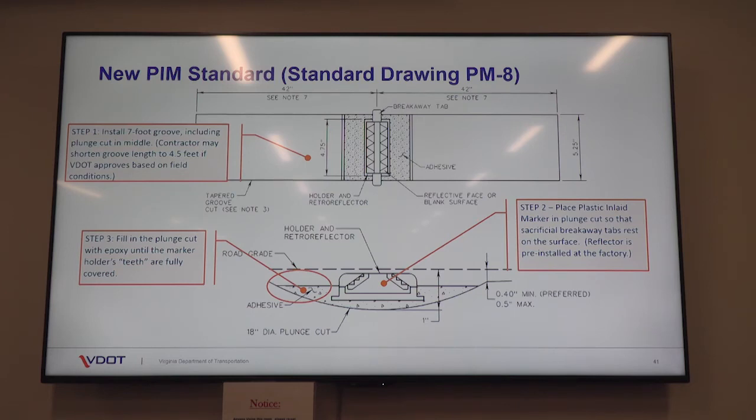Question here? Is there any concern with rainwater getting stuck in the pothole in there? That's a good question. The question, Mark and Harry, was whether or not there's concern with water getting in. So what happens is that when it's poured down rain, obviously it's going to fill up to the extent of the depth of that groove, which is relatively shallow. But as soon as traffic moves, it blows out. So in the limited review that our materials division has done on the test site, the water is blown out, and it's been a non-issue.